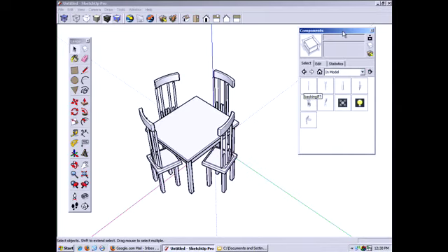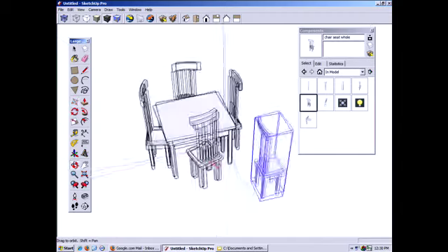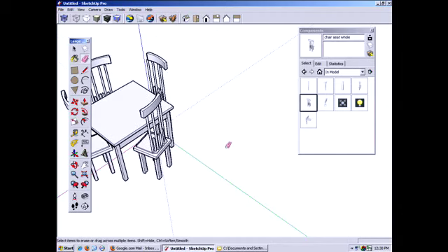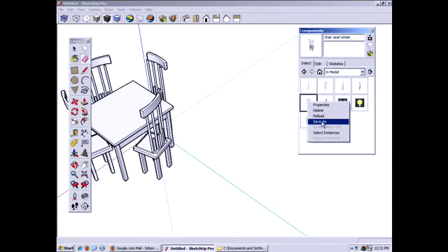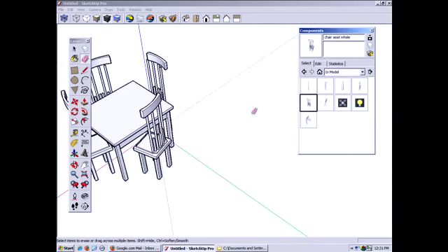So, this component browser, let's say we have the chair, seat, hole, as we named it, is now this chair. And we want to save this out to be able to use in other models. Well, there's various ways to do this. We can right-click on it and say Save As, and I can just save it to my documents or a certain folder, chair seat hole, and I can save it. So you could easily bring that in. But when you're doing entire libraries and this sort of thing, there's certainly a better way to do it.